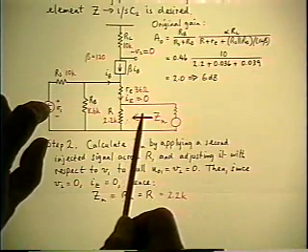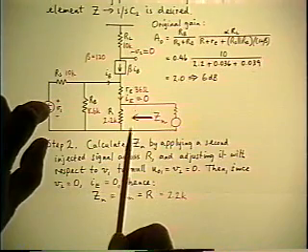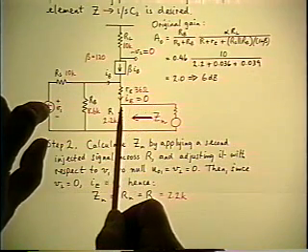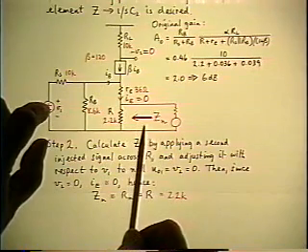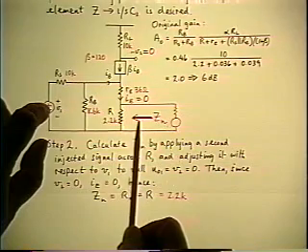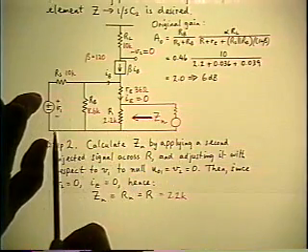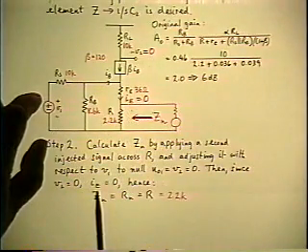Then you take a pair of meters and you measure the voltage across the second source and you measure the current that goes in. And that ratio, by definition, is Zn, the driving point impedance seen by the second source in the presence of the hidden first source, which is adjusted to null the other output.